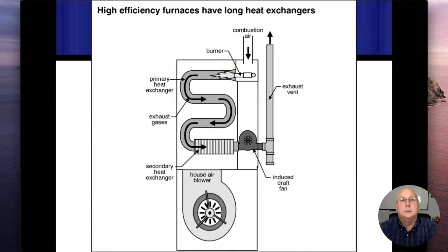High efficiency units and how they start and how they absorb the heat. Typically there's going to be two heat exchangers on these. One is going to be our primary heat exchanger, and that's going to be this looping one. Sorry about that. And that's going to be the pipe that comes down this way. This is going to be our primary heat exchanger. Then it goes into a radiator coil, so it's a much narrower tubing, kind of like an air conditioning coil that goes on there. And that's going to be absorbing the secondary one.